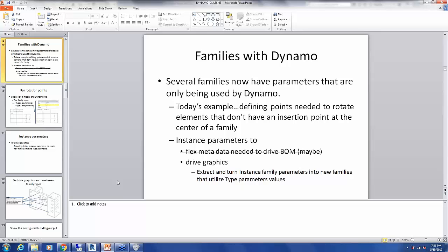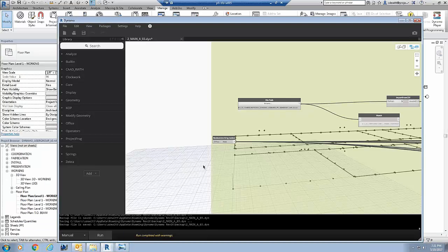I did that because once this goes into production, there's still always a little work that needs to get done inside of the model. So I don't want my users to go in there and accidentally select the family, change the instance, and then copy it somewhere else, because that instance is specific to that exact location in order for part numbers to read right for us. So, and I'm sorry, I know probably some of this is like, what are you talking about? But I hope some of the examples are going to make sense. All right.